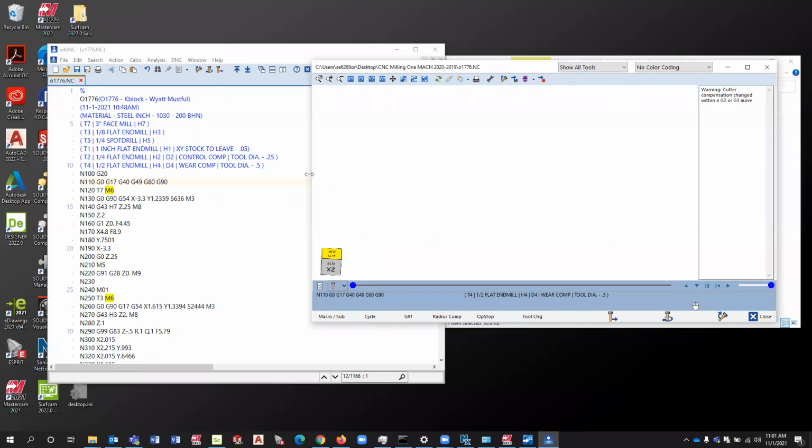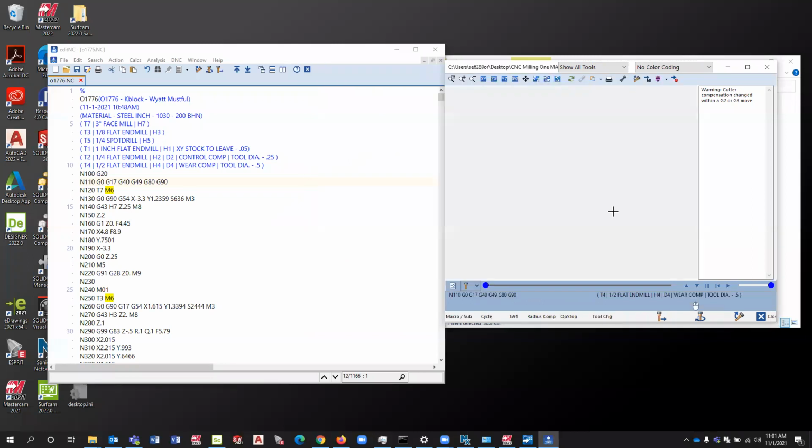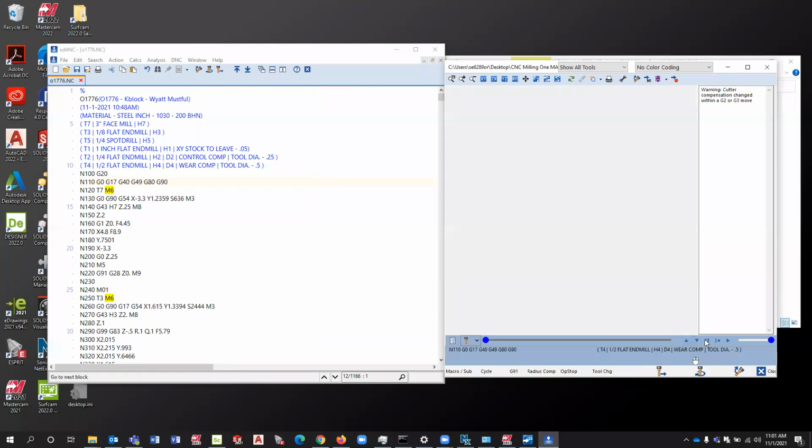This is the newest revision of Edit NC. So there's some new tools here that have not been there previously. So just keep in mind some of these options might be a little bit different, but this is step up and step down. I reset it, and on the left-hand side, you'll notice that there's a highlighted bar on where it starts. And if I press the down, you'll notice that it changed to the next section. And we're just kind of going to go down block by block.